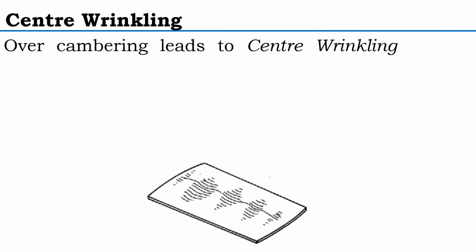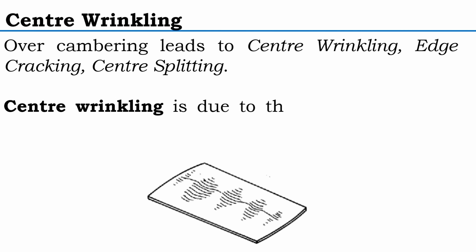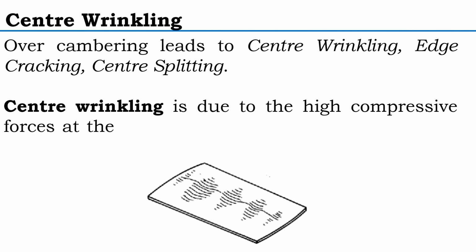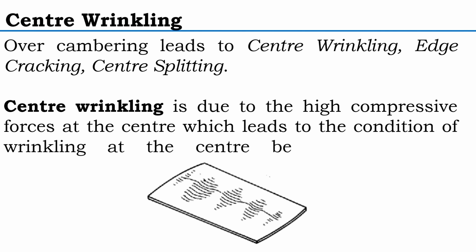Center wrinkling. Overcambering leads to center wrinkling, edge cracking, center splitting. Center wrinkling is due to the high compressive forces at the center, which leads to the condition of wrinkling at the center because of excess compression.